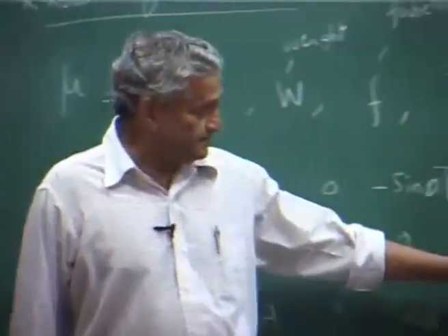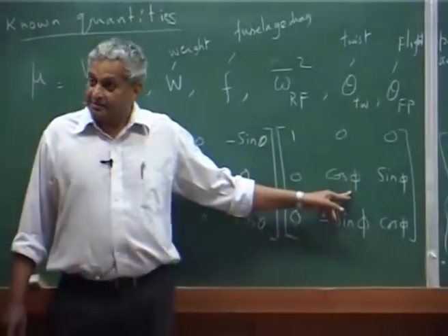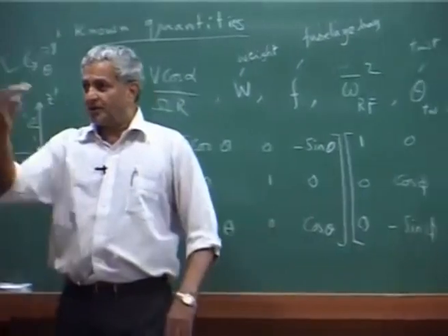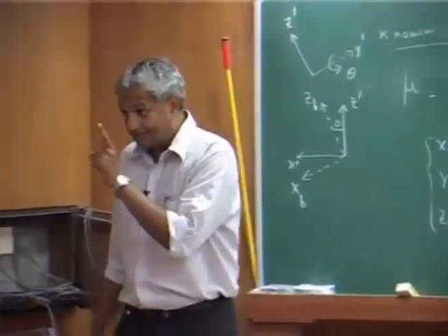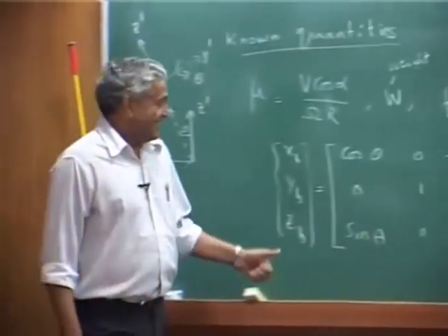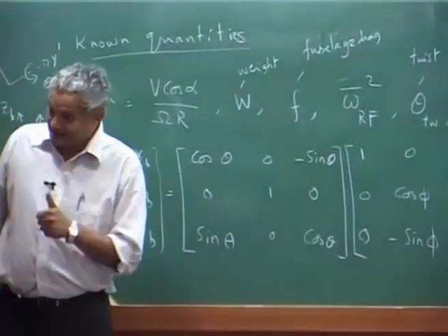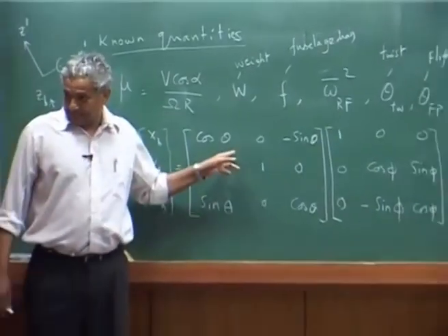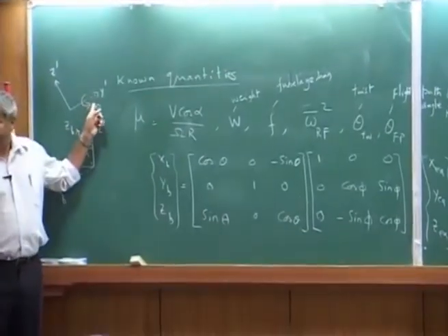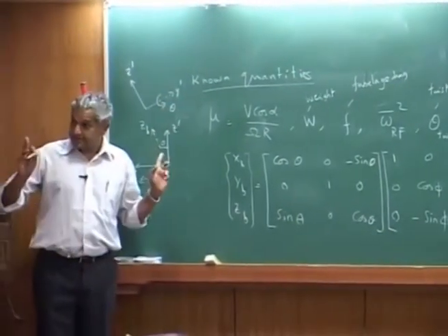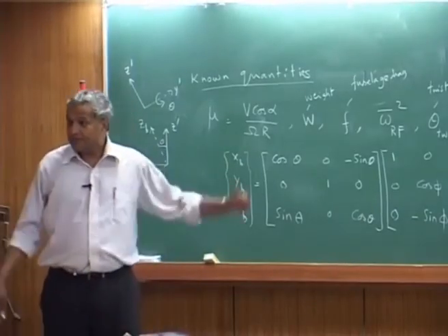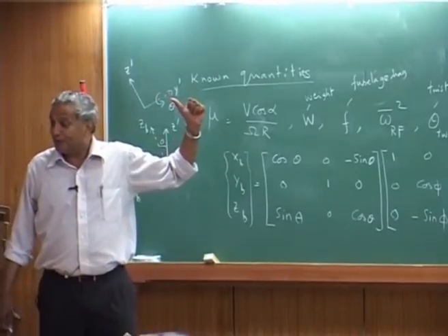This angle is the rotation about earth. I can find out how much roll rate is happening, roll rate with respect to earth, phi dot, okay. How much theta dot is happening here, but theta dot is about the y prime axis, already tilted. Phi dot is about x EA, theta dot is about y prime.